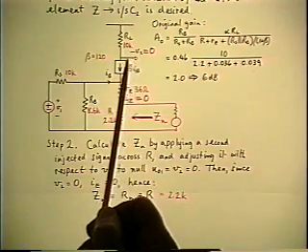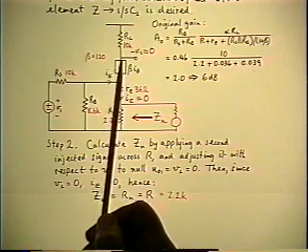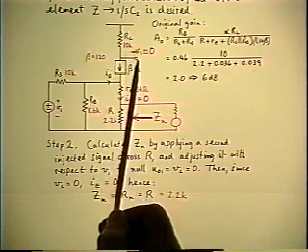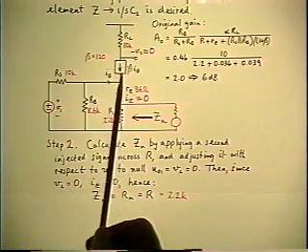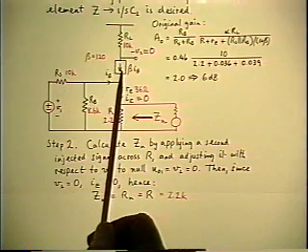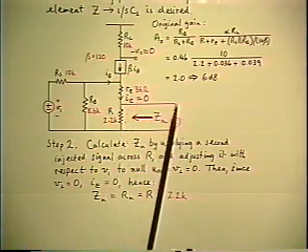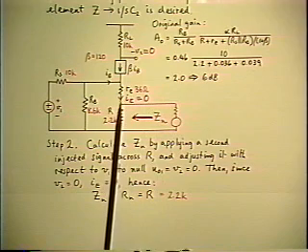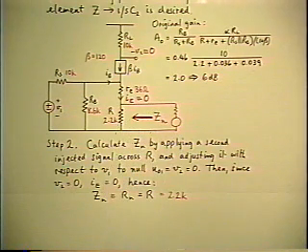So you start with the null, which is an established condition, and you make the following argument. If V2 is 0, there must be 0 current in RL. So there must be 0 collector current. So there must be 0 emitter current. So all of the current from the second source goes down R, therefore Zn equals R. Easy, isn't it?